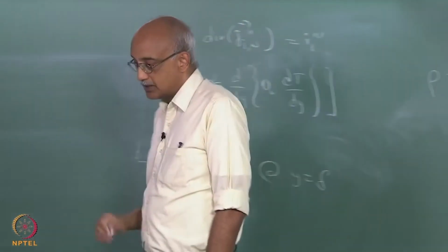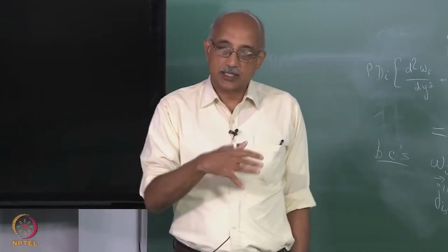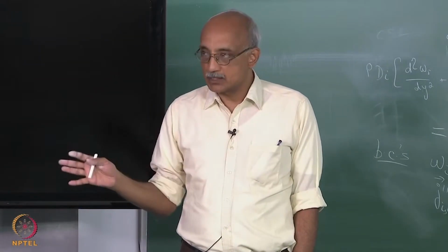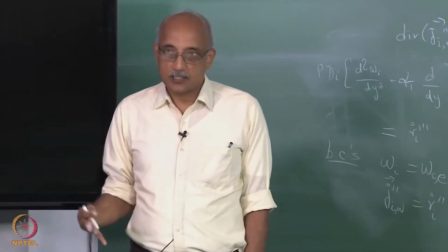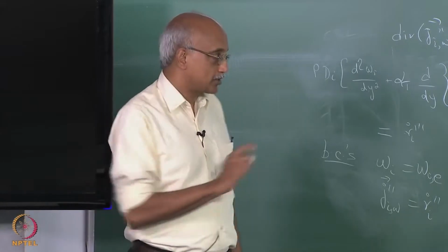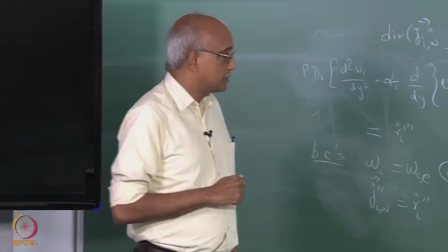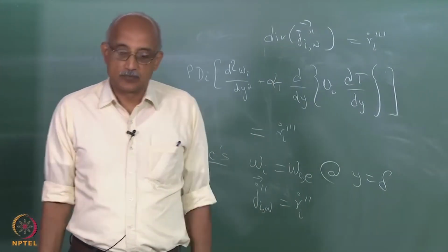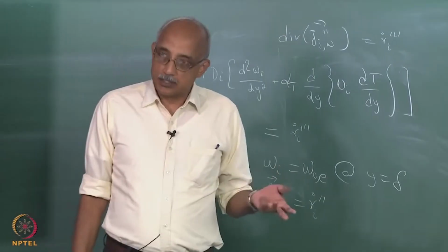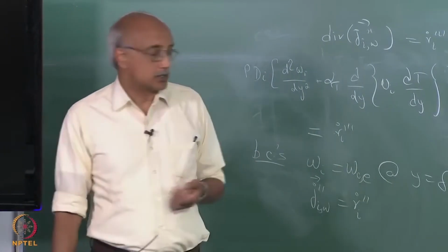Okay. So, in the same set of equations, you have included your homogeneous kinetics as part of the mass conservation balance equation, and you have incorporated your heterogeneous kinetics as a boundary condition based on what happens at the substrate interface. Okay. So, these are your new governing equations for deposition, which account for homogeneous reactions, diffusion and heterogeneous reactions.